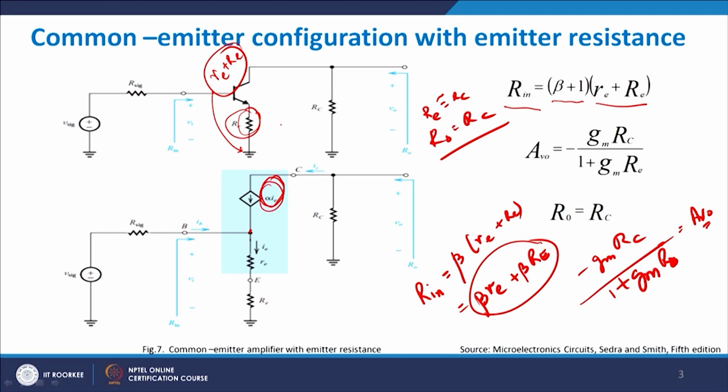The problem with this, technically, is that when you apply a signal on the emitter side, you end up having large parasitic capacitances being extracted even at relatively small voltages, right. And as a result, the speed of the operation will get reduced, right. So, one has to be very cautious when we design a common base amplifier in a small confined domain.